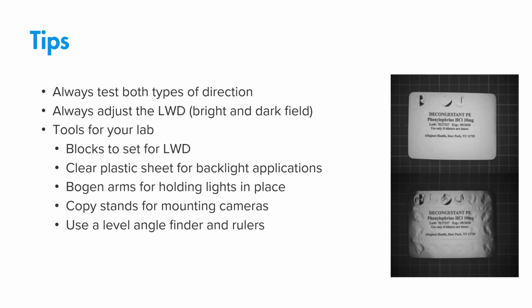The defects are still present, but now they're blending in with the wrinkles that are not defects. In that bottom image I can technically still read the text, so if that's my only goal, either one would work, but the top image is much more repeatable and reliable and will be easier to write a machine vision program for down the line.